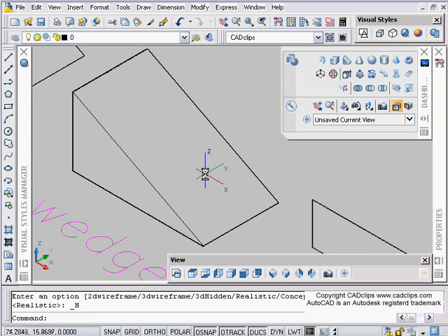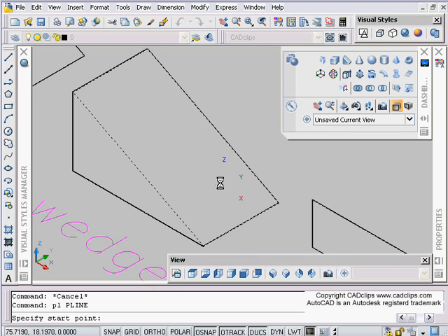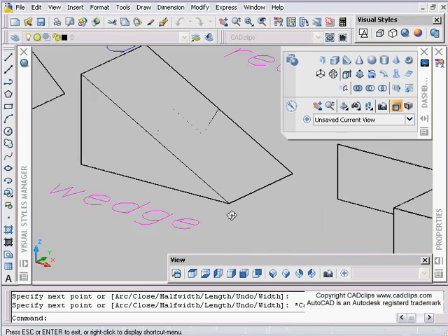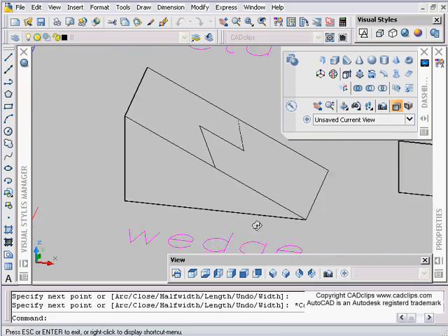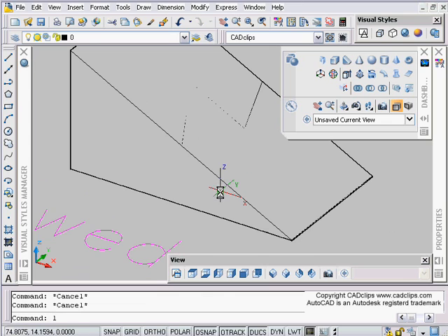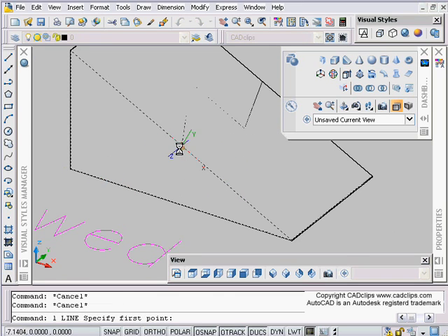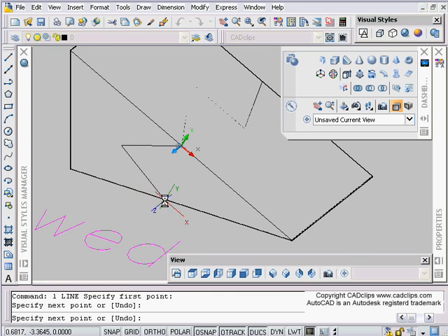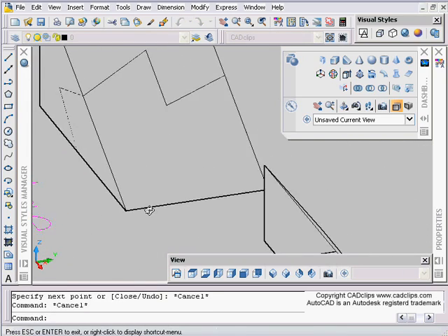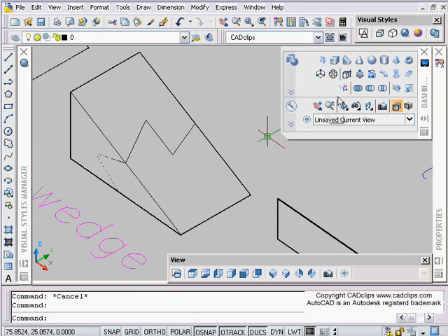you might want to go to a different visual display so you can see your edges, and I can maybe click on here and go over to here, and this could be an arc, it could be whatever I want. Escape. Now shift middle mouse, I know that's on that edge, because I drew the line there, so I can go down now if I want, hover over this edge, draw a line from here to here to here, doesn't matter. Okay, that's just the dynamic UCS.